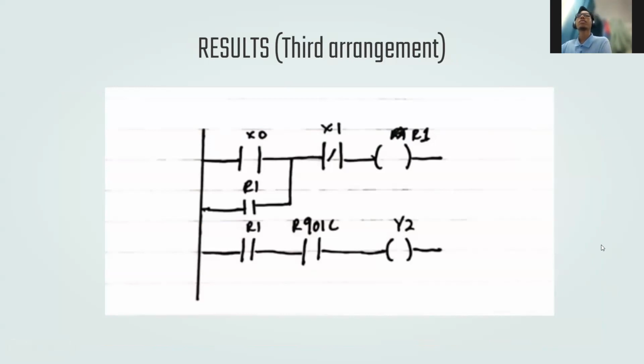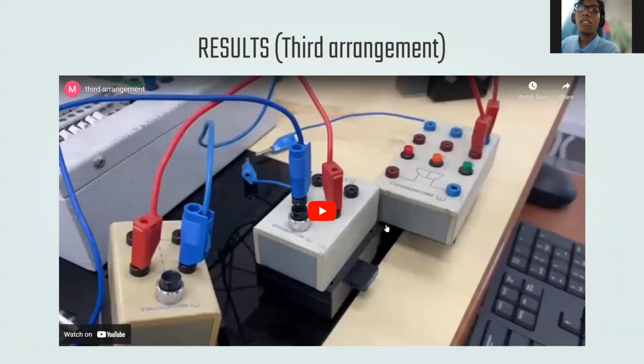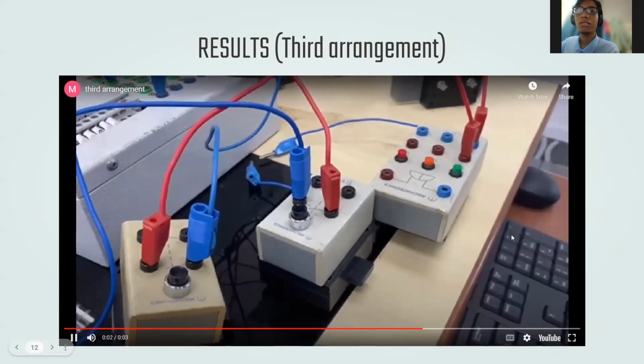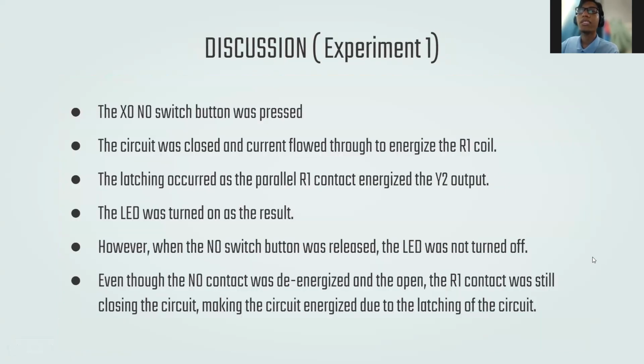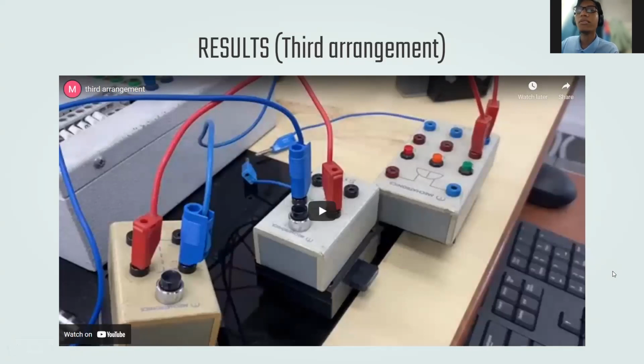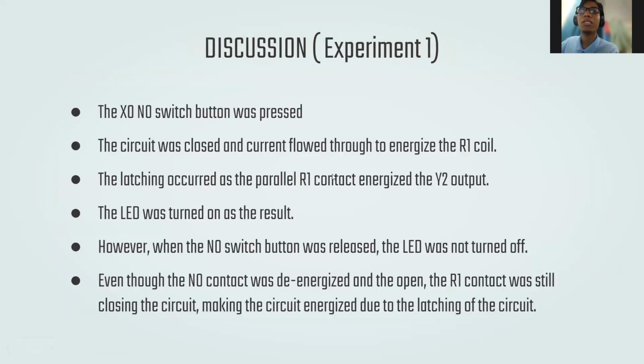So this is the third arrangement. We replaced the timer with a special internal relay, which makes the LED light blink continually after the switch was pressed, and then it was turned off after the X1 switch was pressed again. So next, can you play the video? As you can see in the video, the LED light blinks continually because of the special internal relay. So that's it for my part. I will pass it to the next presenter.